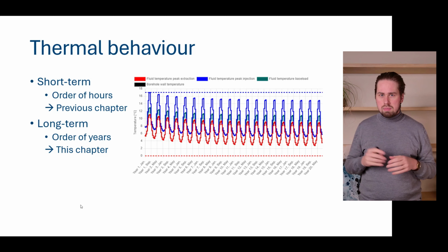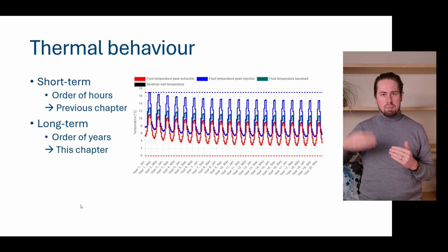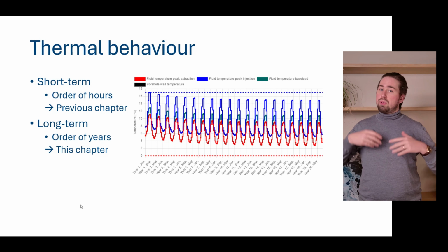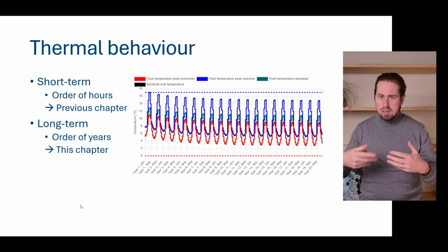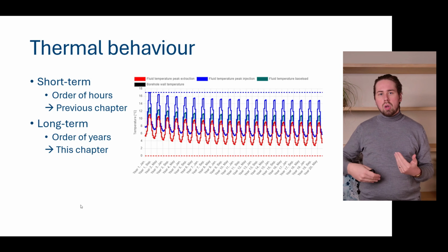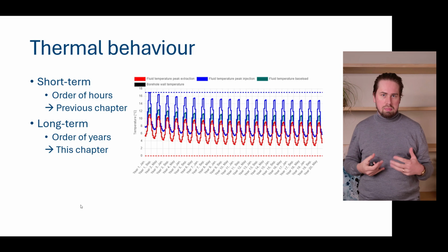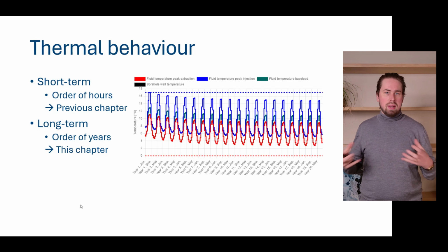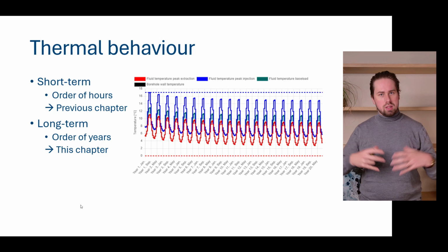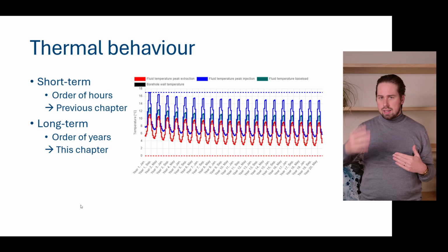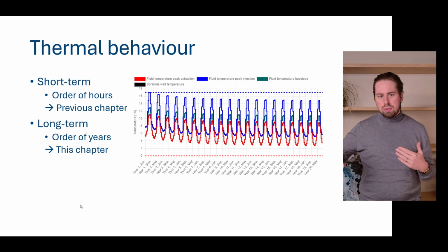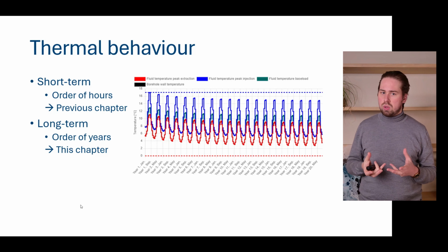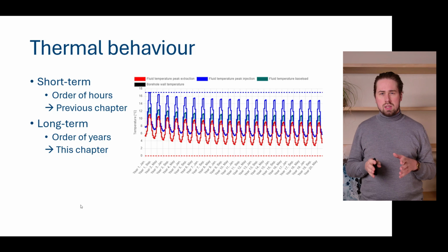Now, on the short time scale, the borehole wall temperature does not change, and it's just the fluid temperature that varies. But of course, over the months, over seasons, over years, this borehole wall temperature will change, because the ground is a little bit like a battery, and it can be charged and discharged. That's exactly the long-term and seasonal variation you see on our temperature profiles, and that's what we will be discussing today.